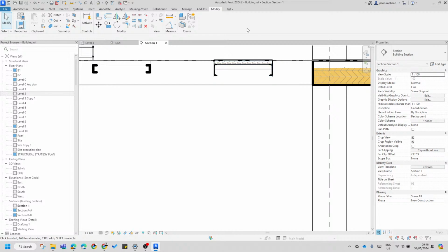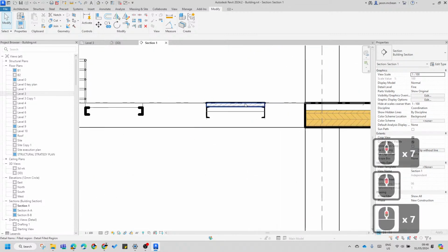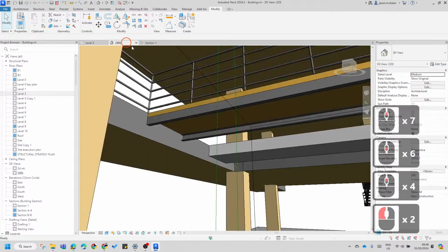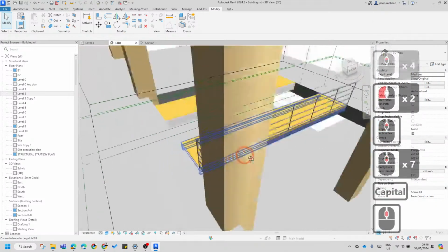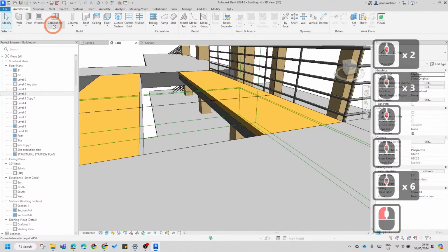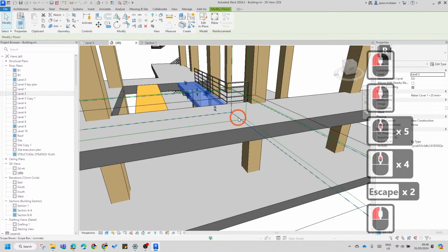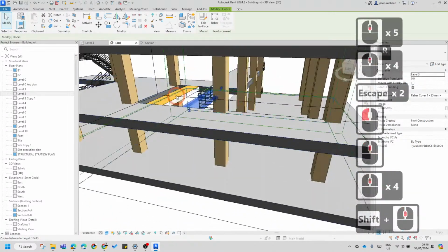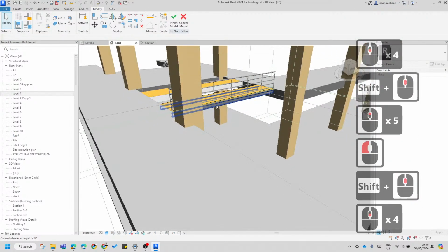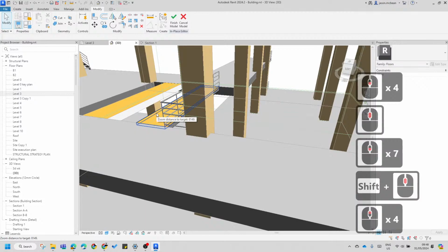Okay. So then, just to double check with that, I create a work plane for that one. Create a work plane, and then once I create the work plane, does it give me those options to create extrusions and all? No, you have to create it. You have to go to architecture, component, model in place. If you're going to make model in places, so now there's a couple bridges. Make the bridges in the same model in place. If I go edit in place, you see this bridge here, and you make it bridge level once. Don't make hundreds of in-place families.